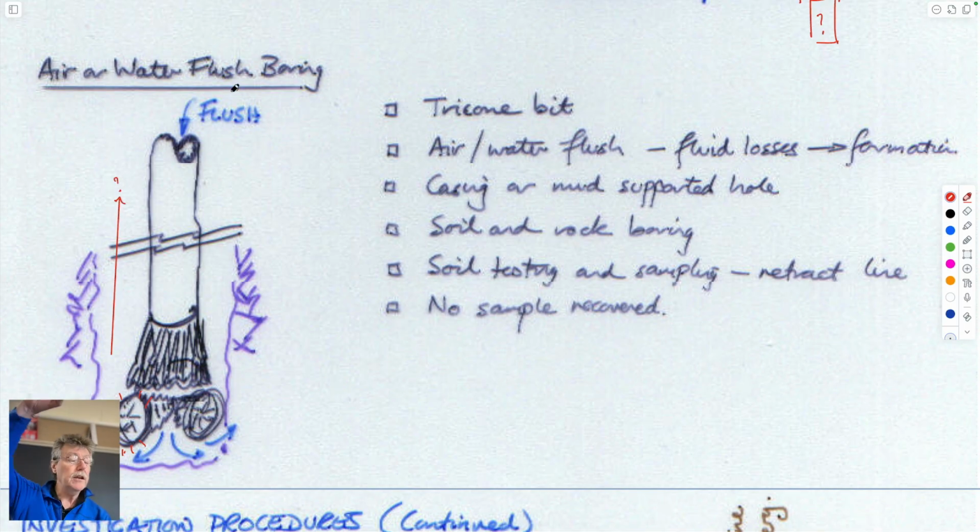You have certain lengths of drill steel down from the surface, so you know which depth you are at. And so these samples that come up, you can either bag and recognize in terms of what the material is, to see what the stratigraphy might be that you've gone through. So again, to build up a picture of exactly what the subsurface looks like and what the depths of these different layers are.